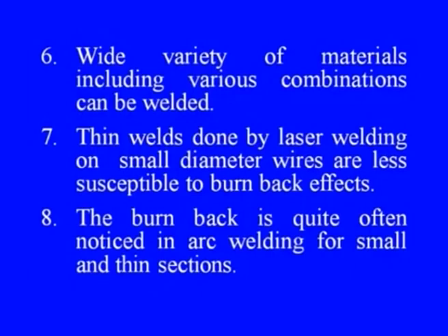Then a wide variety of materials, including various combinations, can be welded by the laser beam welding method. Thin welds done by laser welding or small diameter wires are less susceptible to burn back effects. This is clearly an advantage. Burn back is quite often noticed in arc welding for small and thin sections, which can be easily avoided in case of a laser welding system.